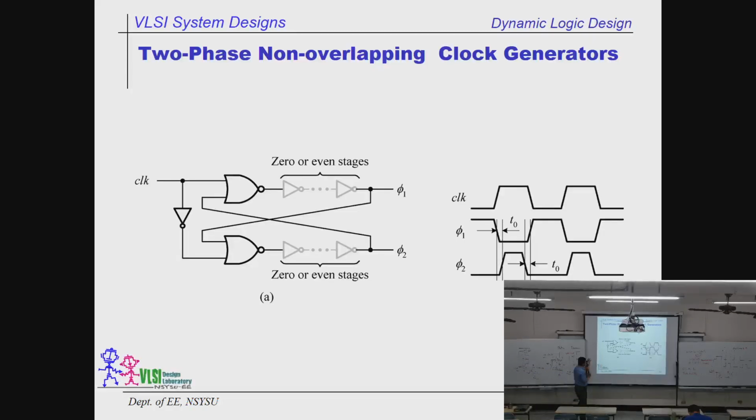How to use that? Brilliant. Clock comes in. This is a flip-flop. Okay, NOR-based, cross-coupled flip-flop. So if you go back and check your freshman textbook in the area of digital design, you know that this is an SR latch, and the inverter comes over here. And you can add a long enough, even number of stages of inverters.